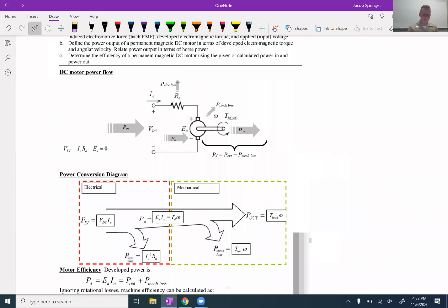Power flow diagram, we have a power in and a power out. This top one is just telling us that we have an electrical power coming into a circuit with a V voltage across it. It has electrical losses, P electrical loss equals I squared R, right? It's not perfect. There's some electrons that don't make it there, but then it comes here, and this is just a diagram of a motor that's spinning, and here's the torque of the load. I keep saying a power drill, but any electric motor that spins.